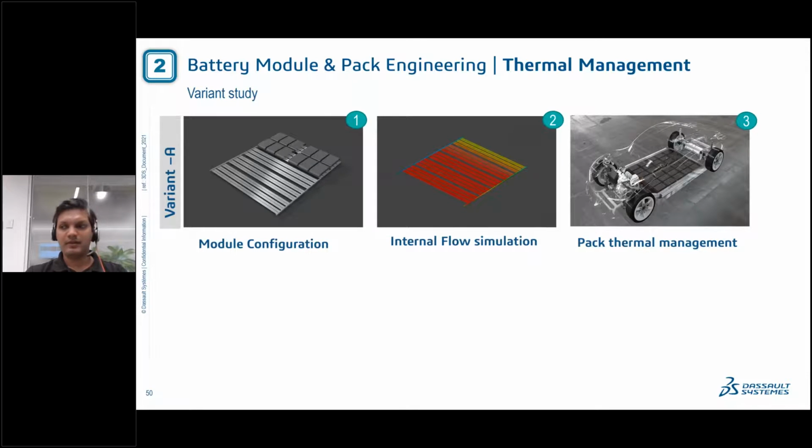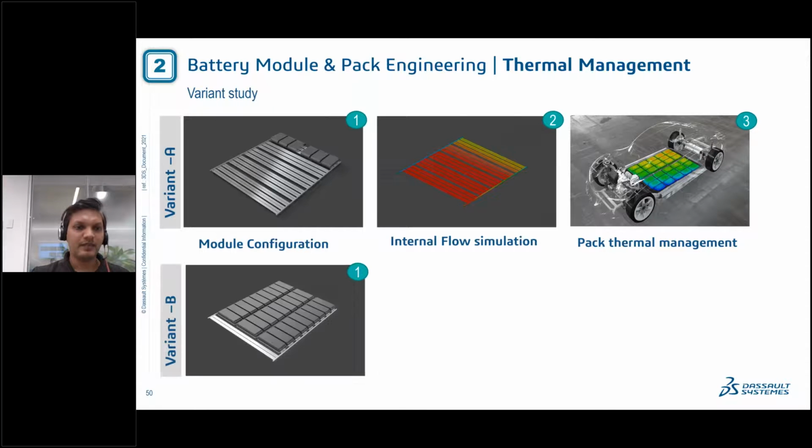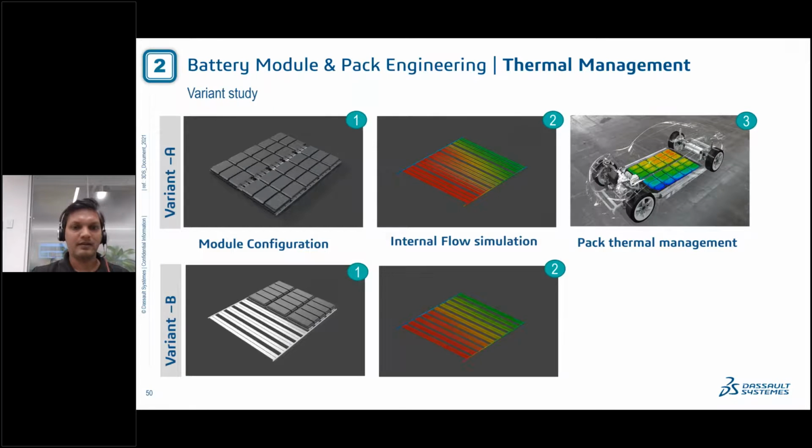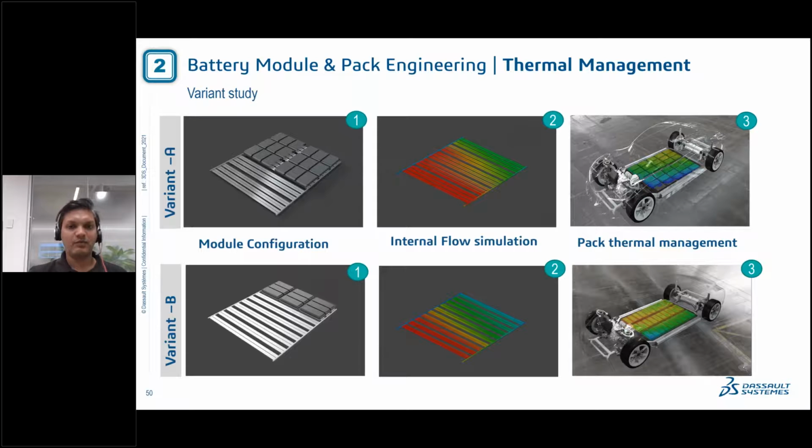So for a given module configuration, temperature propagation or internal flow simulations can be carried out, and also understand the behavior of the temperatures at the pack level within the same platform, and without actually creating multiple files or multiple designs.